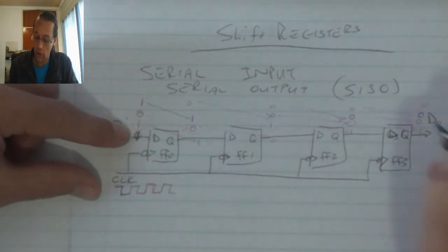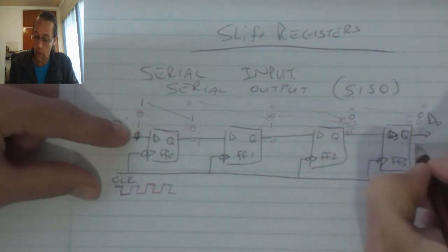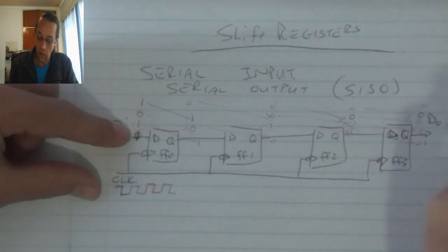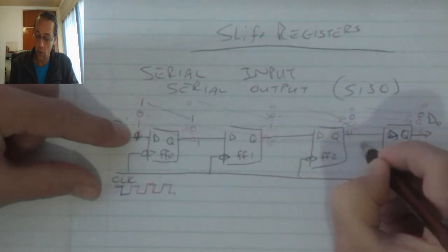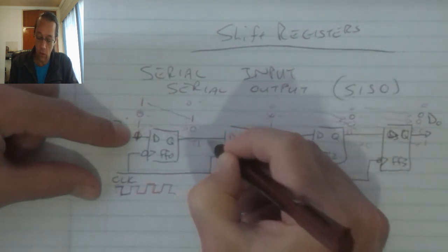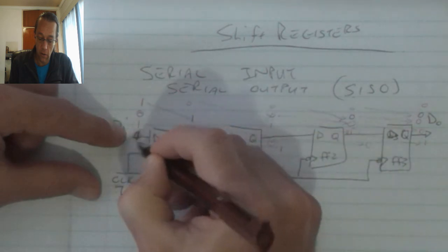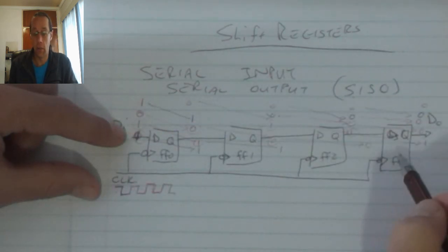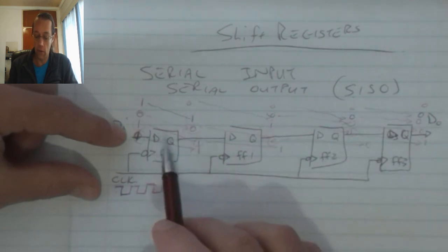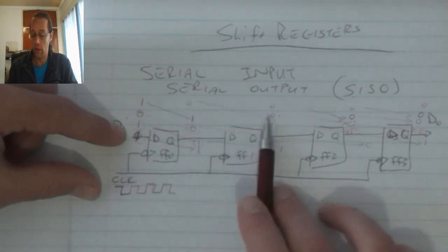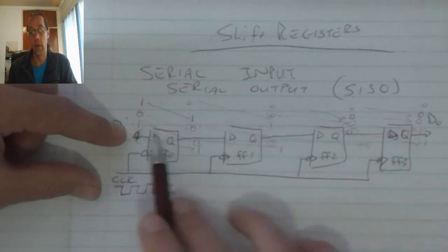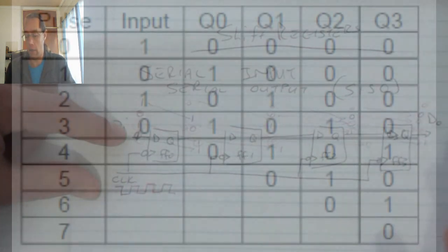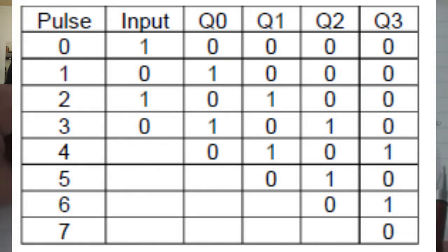With each clock pulse that occurs, my data values move out to the next flip-flop's output. As a result, with each clock pulse, each bit is moved from one flip-flop to the next, and as a result, at the end, we will have all our bits move through our shift register.